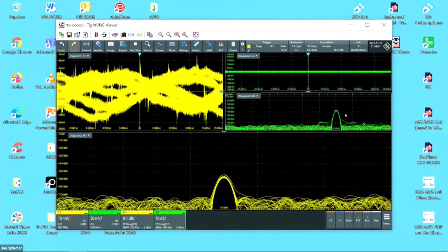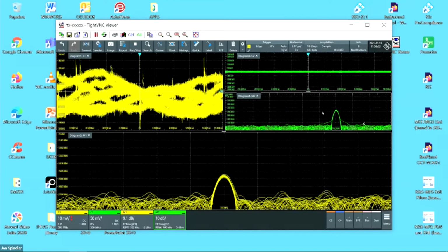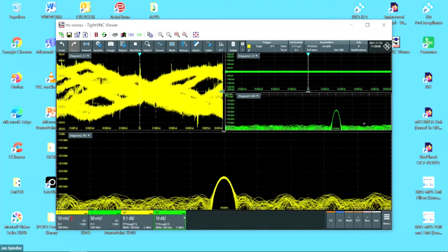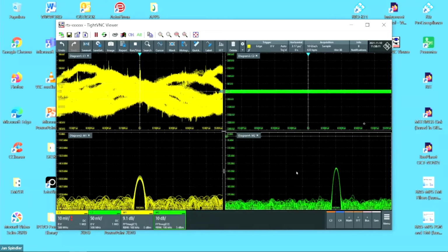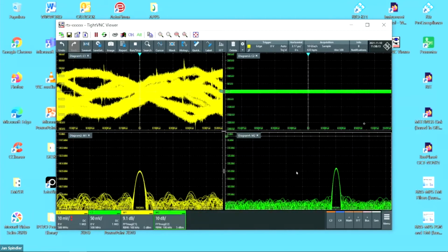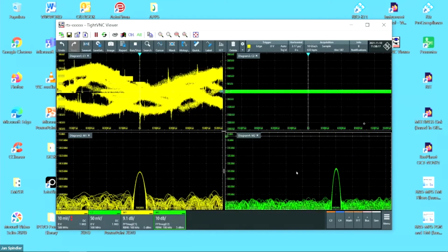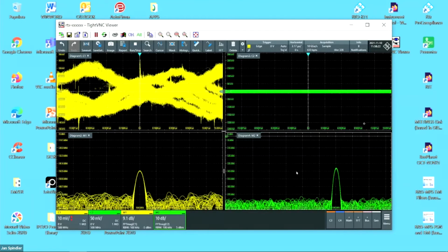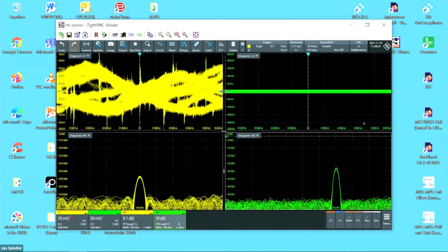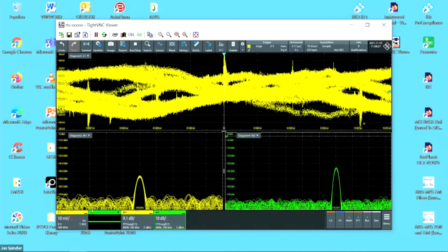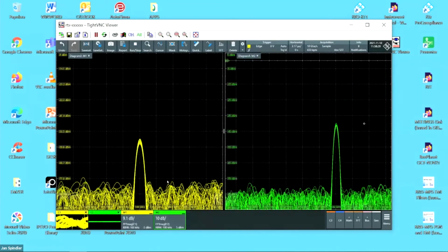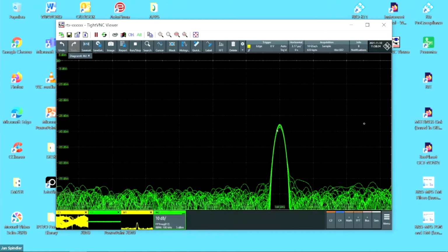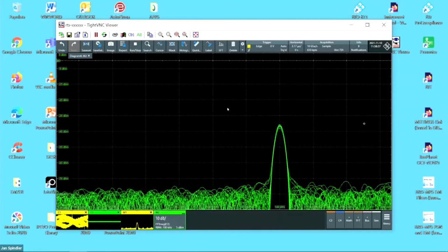Let me see if we see the peak. Here is the peak, okay? So in the cable, I have the same energy, the same frequency, sorry, as in the antenna. If you are failing by 20 dBs with this signal, then you try to reduce this 20 dBs. So let's remove this time domain signal, and let me reduce the antenna signal. This is my interest. Let me save in memory.